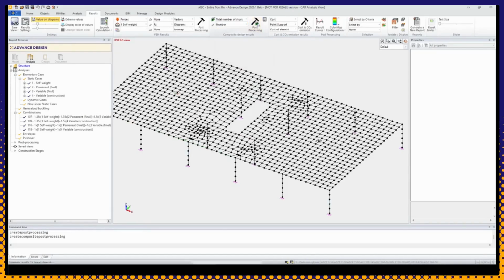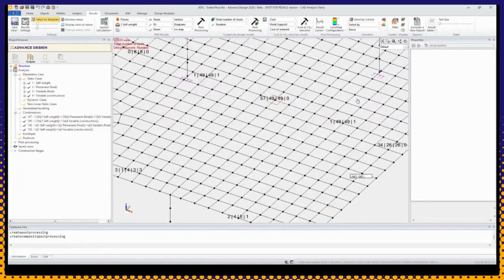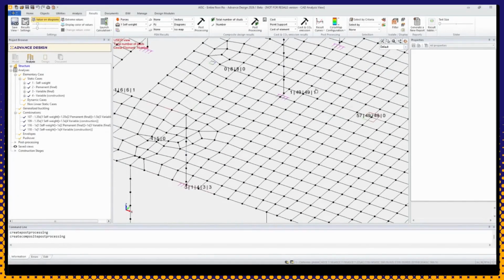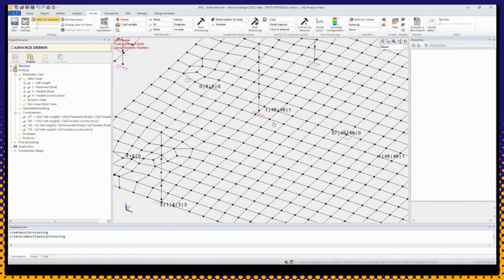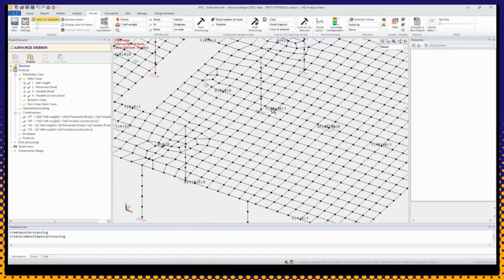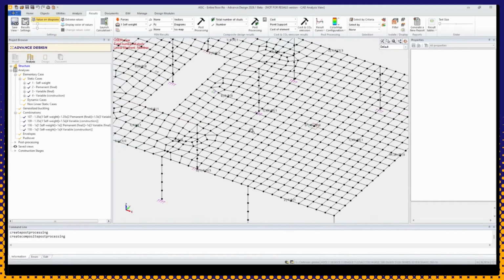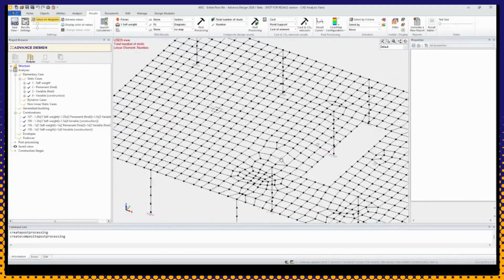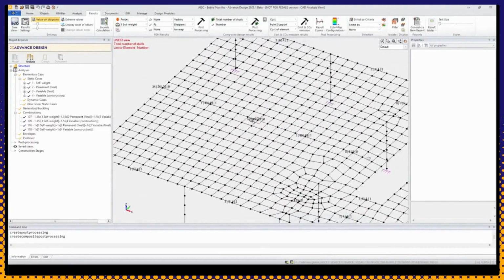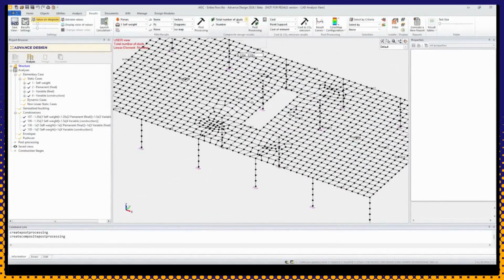And here for each composite beam that I have, you see the number of studs which is needed to cover the shear transfer basically between slab and steel. And you will see the number of rows and number of studs which is needed for each beam here separately. So these were our graphical results for this example here.